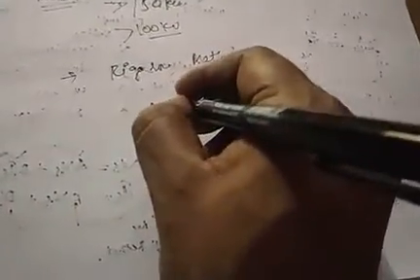It means you don't know how much length it is. So definitely you should maintain that the transmission line parameters are distributed parameters throughout the length, because you don't have any minimum length. It's a long length, right? Definitely you should consider this. So for this we have a method called a rigorous method. We'll discuss the rigorous method in the next unit. All the derivations of the ABCD constants are for this. With the help of the rigorous method, you can calculate the ABCD parameters.